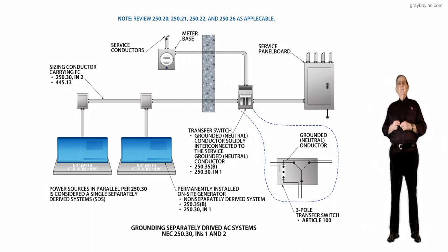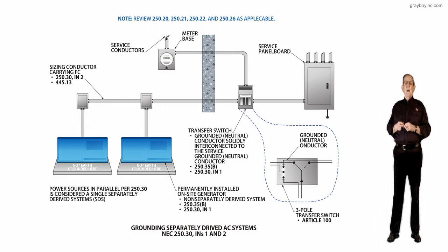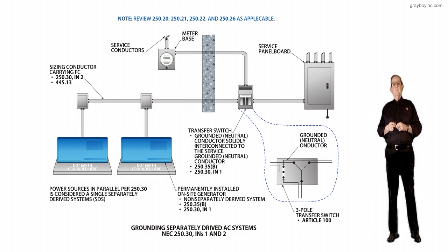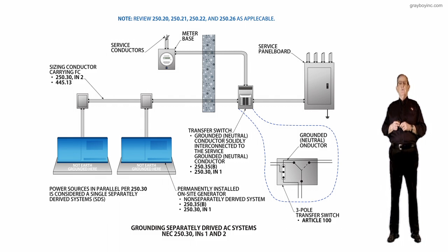445.13. And then you would look at Table 250.102(C)(1) if you were connecting to the windings instead of a main. If you're at a main, you'd look at Table 250.122, as it tells you to do in 250.35(A) and (B). So you would review the type of transformer that you have, as I just quoted to you.